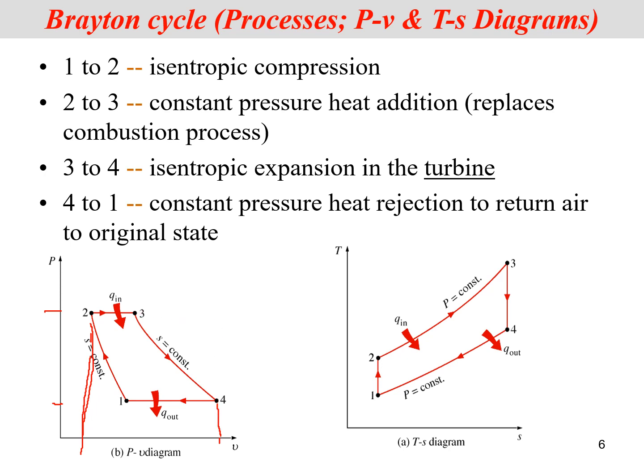So the most ideal work input and output process we have discussed is the isentropic process. And we have discussed that because of the limitation of a reactor and the heat exchanger, we can only have constant pressure heat input and heat output processes. So the Brayton cycle just employs all four of these.